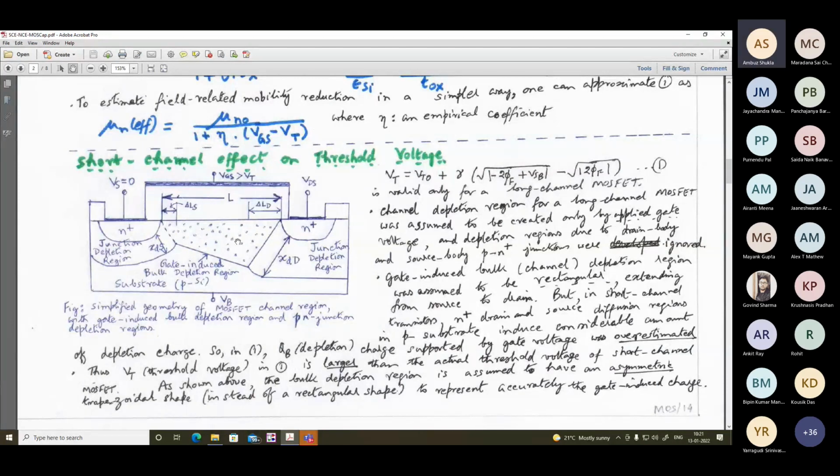One is due to the VGS. That means this is called the gate induced depletion region, right? As you have studied earlier, as the gate becomes progressively positive with respect to source, we go through first the depletion phenomena followed by the inversion phenomena, right? So in the depletion phenomena, we showed that a depletion layer will be uncovered slowly. Well, all of us, I believe, will remember. So this depletion region will assume this shape.